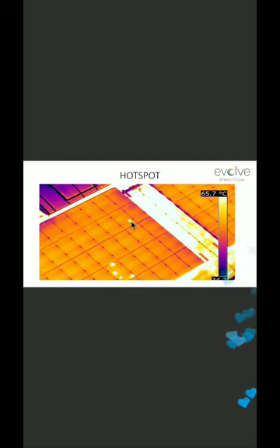So the cell starts emitting the heat. When it is emitting more and more heat, at some point the backsheet behind the cell is going to crack. Then the backsheet will crack and it may seriously damage the electrical busbars. And when the backsheet is cracked, it may lead to a leakage in the system. If there is improper grounding, the leakage will be a very big issue. Very, very big issue. So that thing should be called a thermal hotspot. When the thermal hotspot is created, as already discussed before, the cell starts consuming power rather than generating.